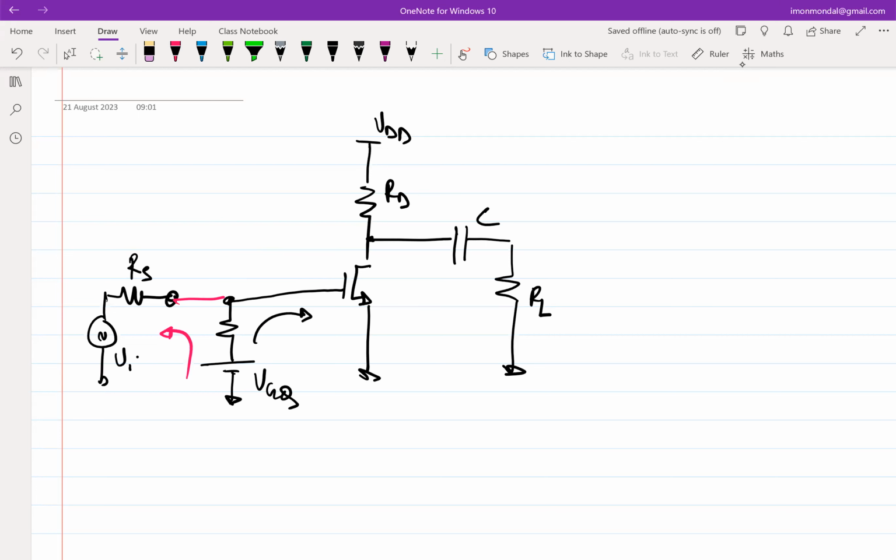And one of the suggestions was to raise the value of VGQ. Do you remember that? Yeah. So one of the suggestions was to raise the value of this voltage so that this voltage increases, and also to ensure that, let's say this is, I don't remember what I called it in the previous lecture, but it's called R1. If R1 was also raised sufficiently, then the entire incremental VI would have appeared across the VGS of the transistor, because from the perspective of VI,